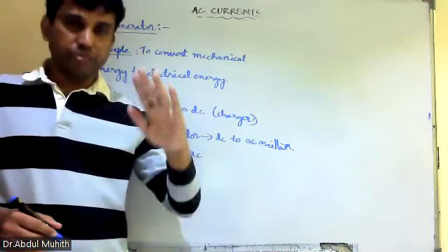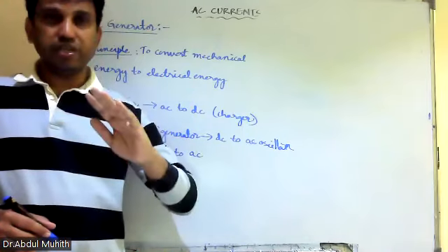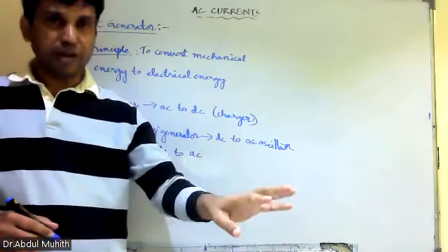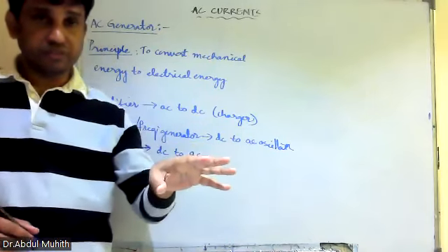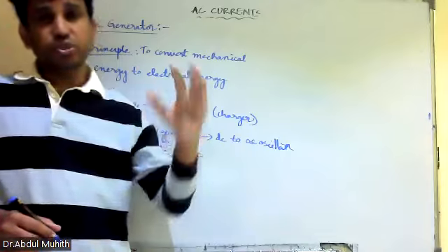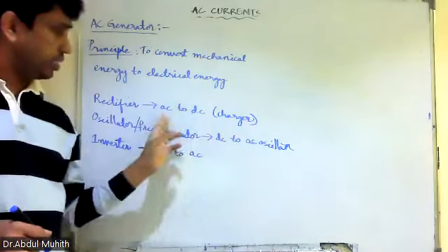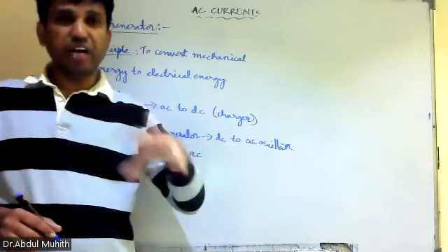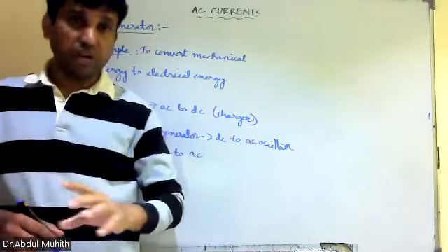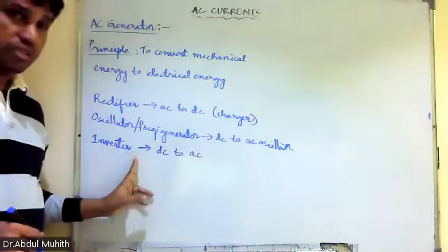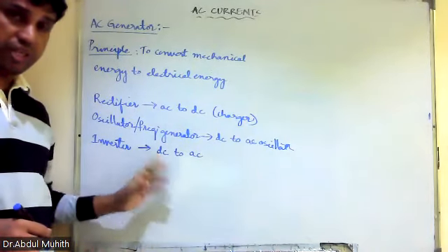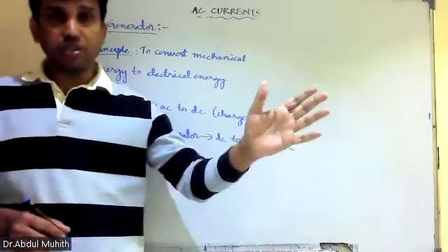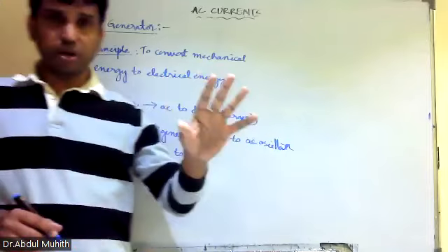Rectifier, whenever the power is there, the current is converted from AC to DC and stored in the battery. In battery, we cannot store AC current. We can store only DC. So it converts from AC to DC, and that energy is stored in batteries. When the power goes, the inverter comes into action. Whatever energy is stored in the battery, it converts DC to AC and supplies to the tube lights or the fans wherever you have fixed this.